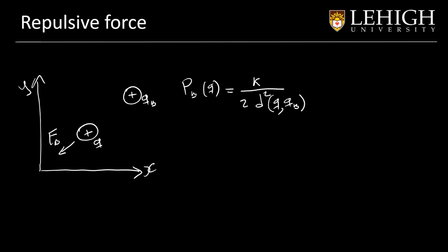If the robot is close, the force should be very large, and if the robot starts to be farther, that force should go down and down. So if we are very close to an obstacle, we want a very high force that pushes us out of the obstacle.